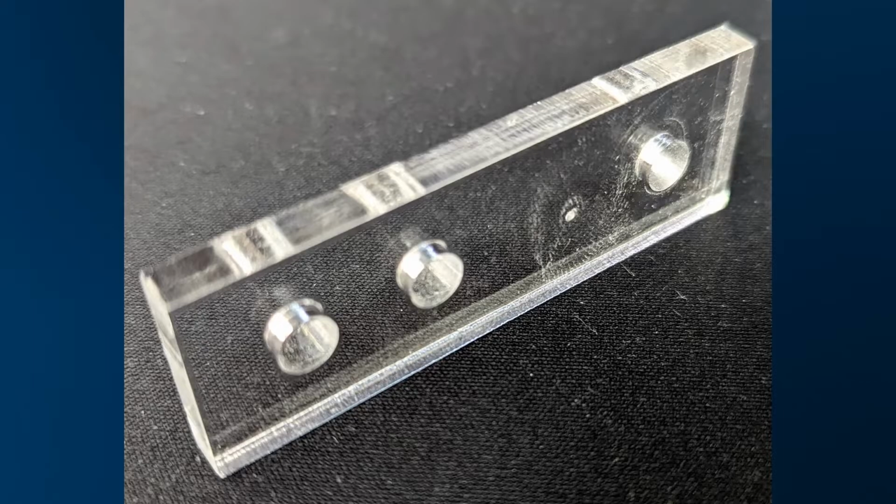The laser is putting a tremendous amount of energy in a very small space. And when you dump lots of energy, in this case heat, in a small space, you get a chemical party, and almost every kind of reaction you can imagine is going to happen inside the machine. So the chlorine from the PVC is going to form all kinds of strange products, and a lot of those are going to be corrosive. On the plus side, a lot of the things that are actually toxic, you're going to be able to tell because they're going to smell absolutely horrific. You're not going to want to be in the same room with the machine.